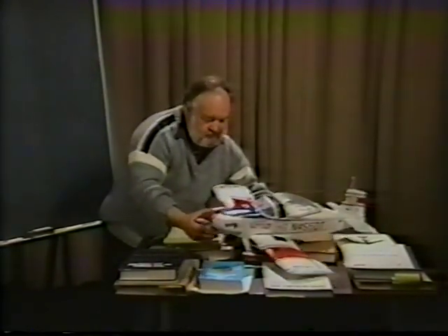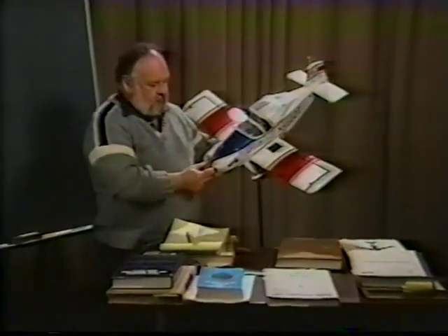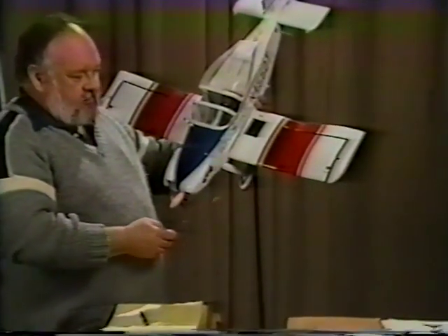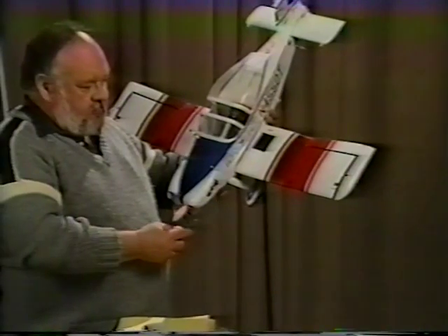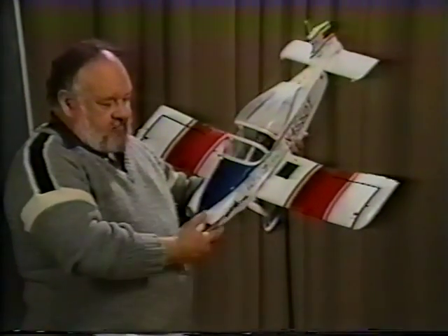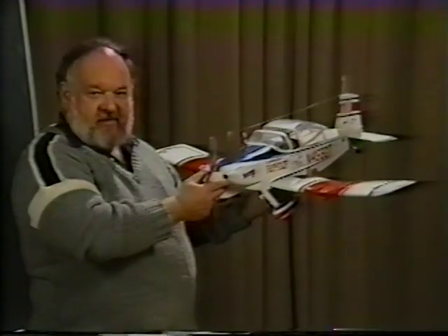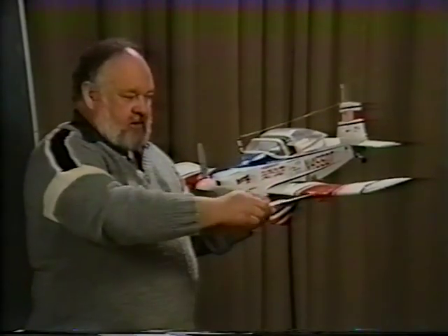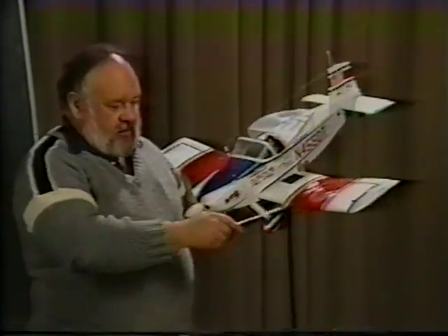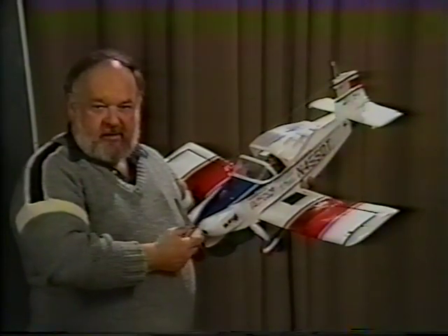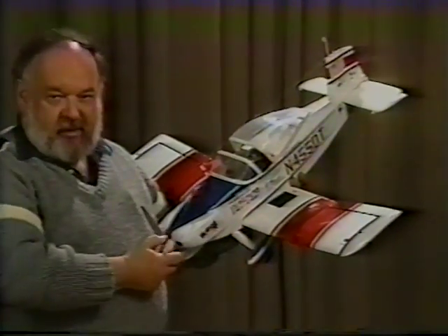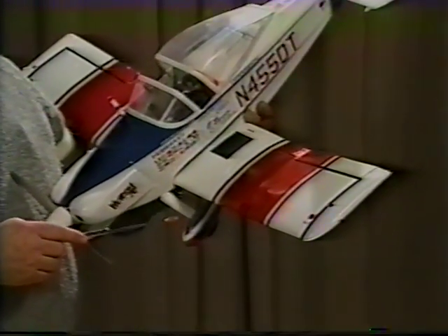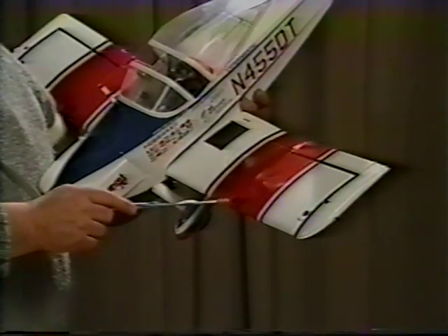For example, it has a straight chord wing, essentially a rectangular wing planform, with a straight leading edge. It does have polyhedral to the extent that the inboard section has no dihedral and the outboard section does. Right here, where there's a break in the dihedral, there also is a slight break in the leading edge itself. So this region will probably be an area where the stall pattern will start to begin.